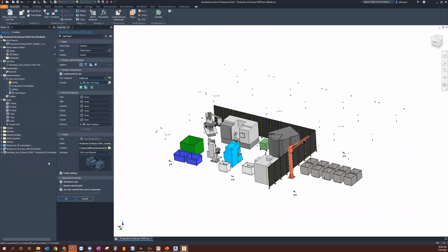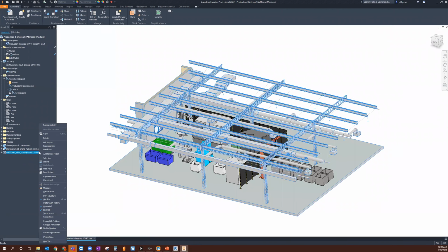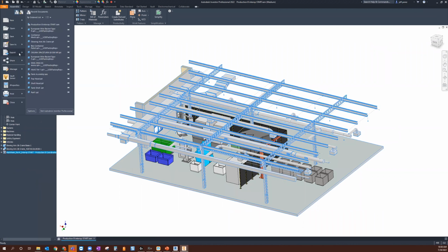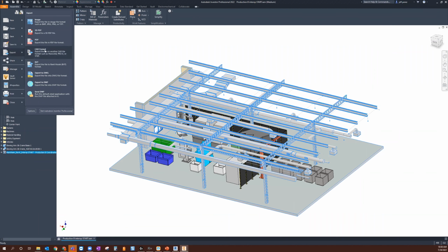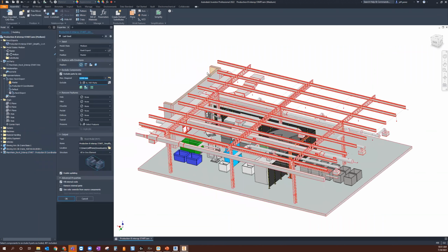I'm going to do one more, and I'm going to show you really quick. I'm going to turn on the building this time. So I'm going to turn back on the visibility, just going V for visibility. Sorry if you're not seeing that. So I'm turning back on that visibility, and we will do one more export really quick. I'm going to do it under my export tool here. And then make sure it's on there, my medium Revit export. And then I'm going to give this a quick new name, BLD to include the building into it, and we'll click OK. We're just doing one more export.